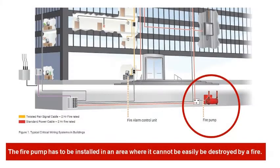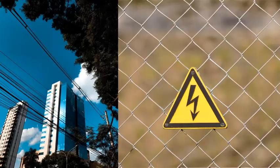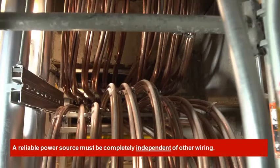For example, you don't want to install the fire pump inside a building where it could easily be destroyed by the very fire you're trying to put out. Minimizing or even eliminating its exposure to fire is a principle that makes total sense. The same thing goes for the requirement that it has a reliable source of power. A little less obvious is the requirement that its wiring be independent of other wiring, but when you think about it, this also makes sense as well.